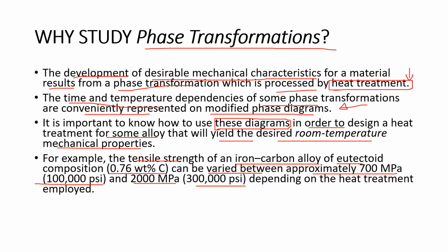If we combine it with carbon, we can improve the mechanical properties from 700 megapascal to 2000 megapascal, depending on the heat treatment used.